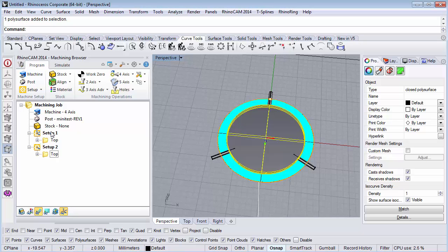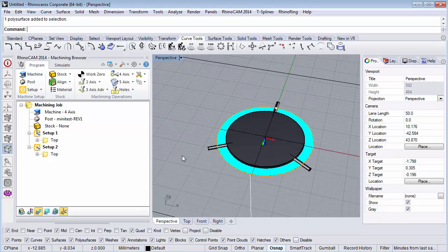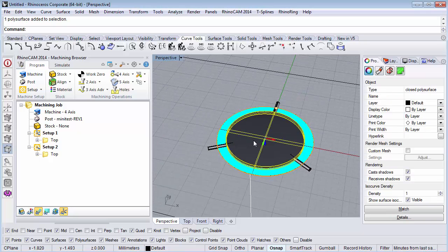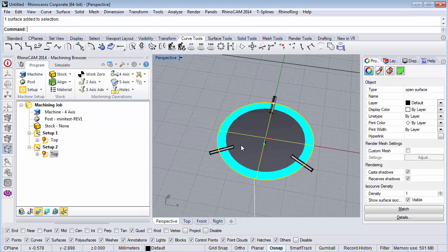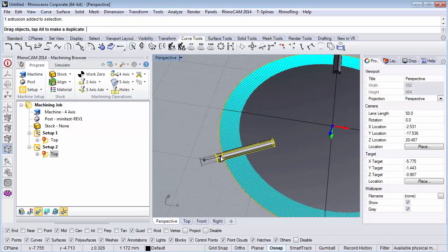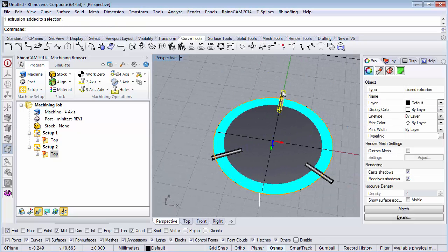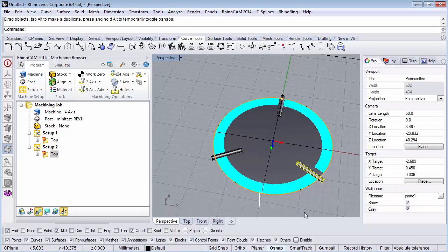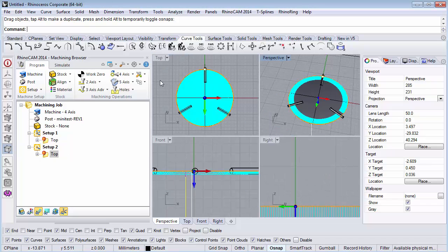So without having to do everything that I just went through manually, you could save this file as a template and simply delete this part each time, okay, and make these longer till they touch whatever part you put in it. So you could swap out parts as frequently as you liked. You could put this pendant in there, you could put a disc hole, you could put whatever you want. Once you've done this once, it's not finished. All right. So let me put something else in there just to show you what I mean.